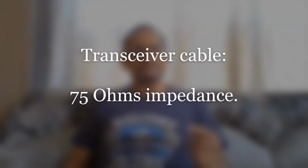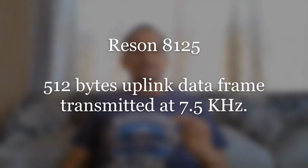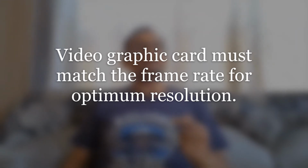The maximum cable length between the transceiver and the sonar processor is between 15 to 30 meters. It is of particular importance that 75 ohm impedance is maintained throughout. For newer systems, the uplink between the transceiver unit and the sonar processor is a digital data stream of 38 Mbps or even more. In Reson 8125, the uplink data frame consists of 512 bytes transmitted at a frame rate of 7.5 kHz. On screen, a higher frame rate produces a smoother video and a high-end video graphic card is required. Otherwise, all the talk of resolution won't amount to much in terms of the visuals.